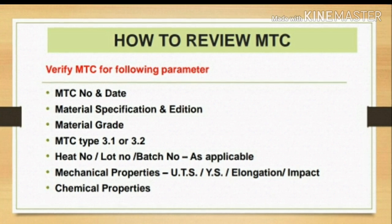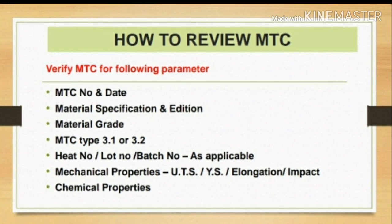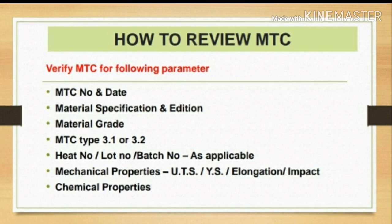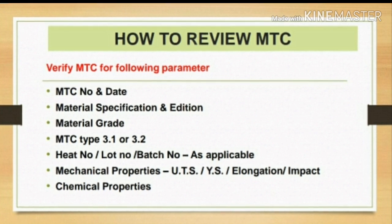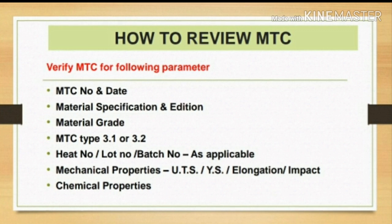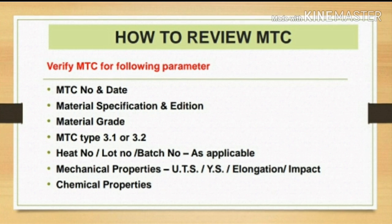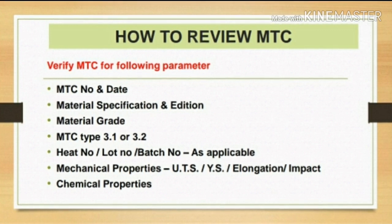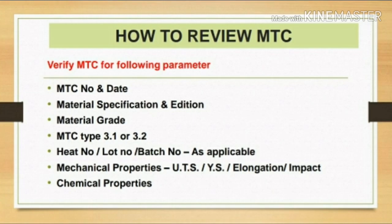So first point is MTC number and date. Then next point comes material specification, material grade and edition of material specification. Then third point comes MTC type. There are various types as per BS EN 10204. So generally type 3.1 and type 3.2 TCs are acceptable by oil and gas customers. Then in every MTC, heat number, lot number, batch numbers are mentioned. So we QC engineer has to verify this with respect to actual material. Then in MTC, mechanical properties like ultimate tensile strength, yield strength, elongation and impact properties are mentioned. Chemical properties are also specified in the MTC.